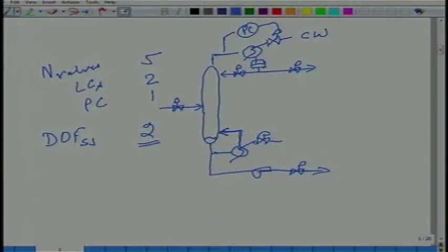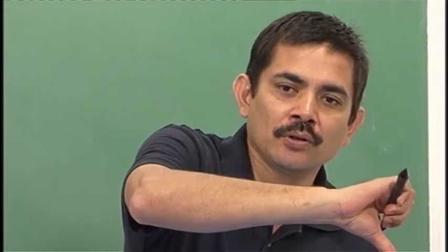Usually that is the case. In some unusual circumstances, he may adjust the reflux or reboil indirectly by adjusting the distillate rate or the bottoms rate or some such combination. Those combinations are also possible, but basically he has got 2 things in his hands: how much liquid is being put into the column, and how much vapor is being put into the column.